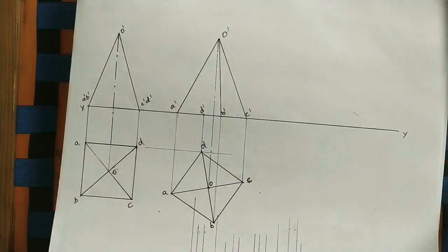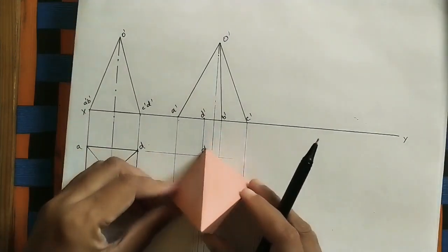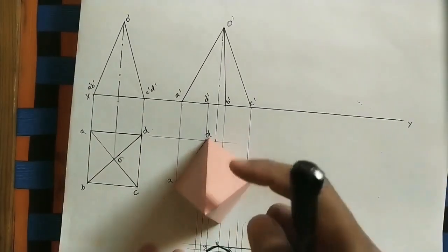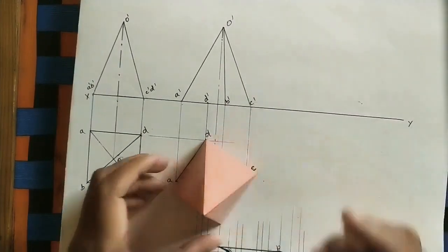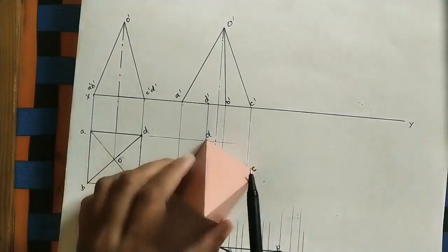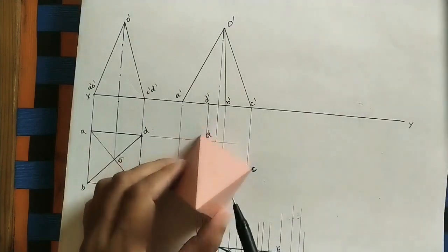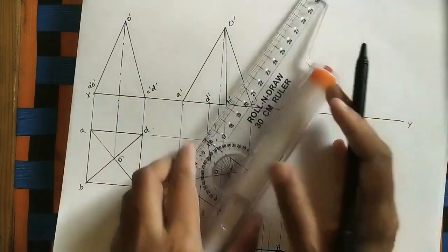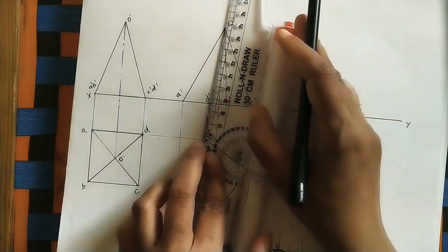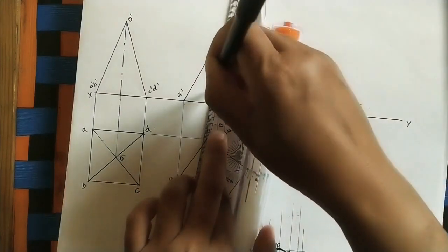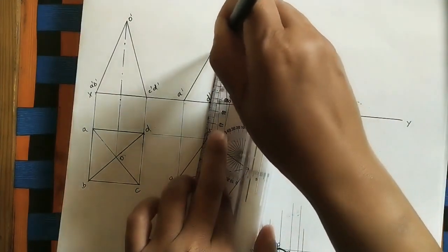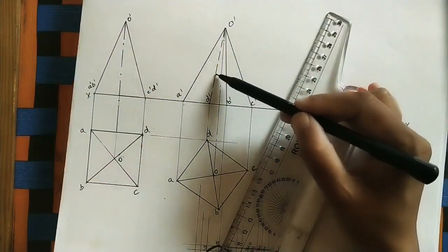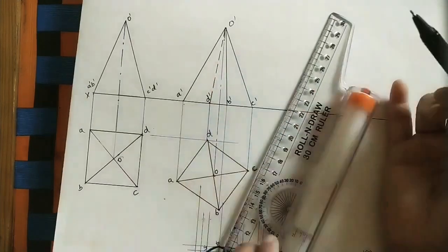Okay. Now if we take the solid here, like this, whatever D is coming from the front, from this front side, we can't see this D edge. Okay. So we can see this inclined edge from B. From D we can't see this edge. So whatever line is passing through D, it is a dotted line. So always remember, invisible edges are with dotted line. Dotted line means dashed line, like this. Always remember, this dash should have equal length, and this gap is also equal length at all places.